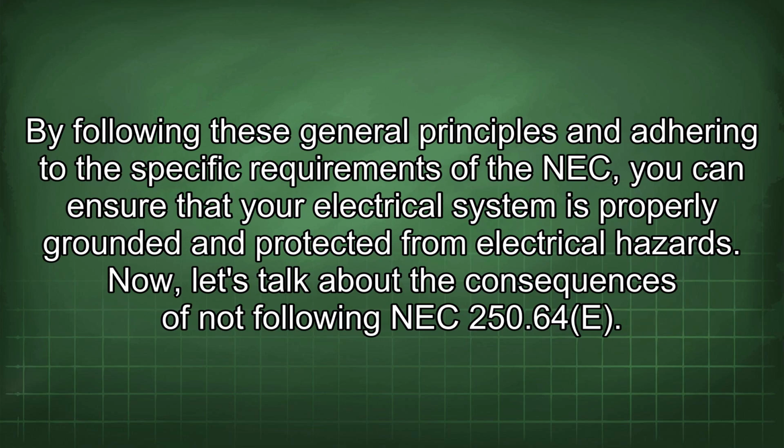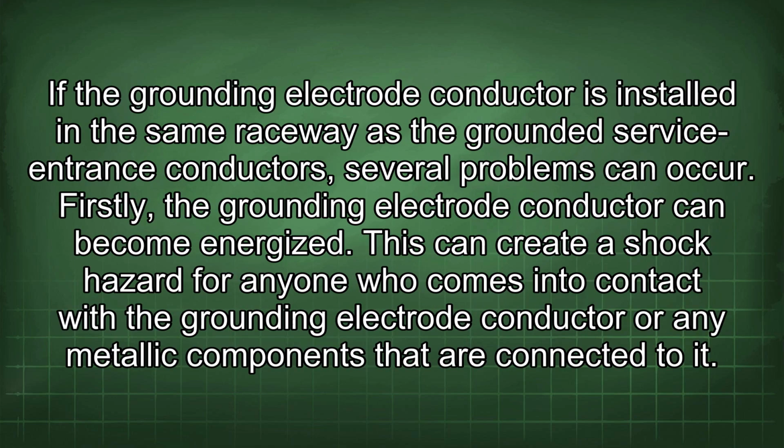By following these general principles and adhering to the specific requirements of the NEC, you can ensure that your electrical system is properly grounded and protected from electrical hazards. Now, let's talk about the consequences of not following NEC 250.64e. If the grounding electrode conductor is installed in the same raceway as the grounded service entrance conductors, several problems